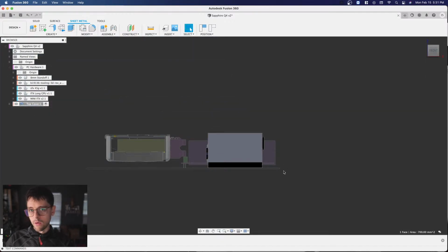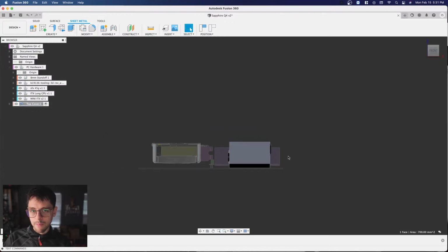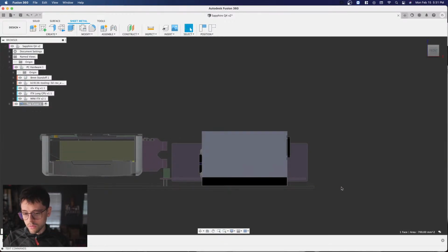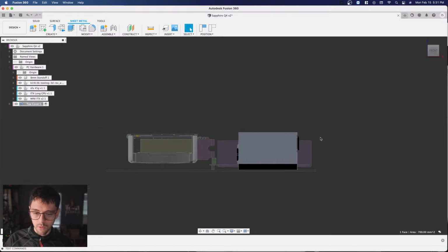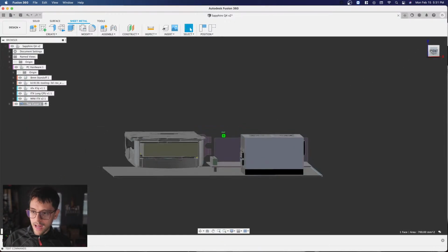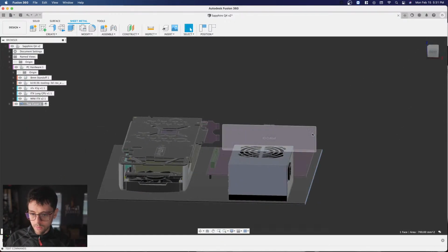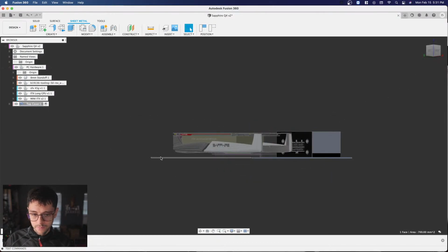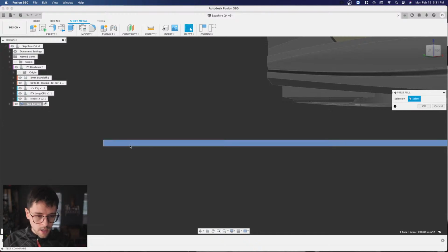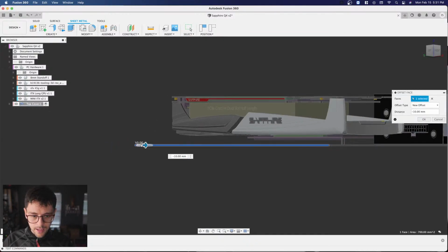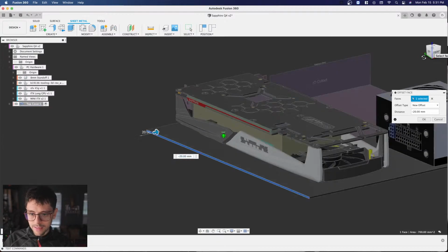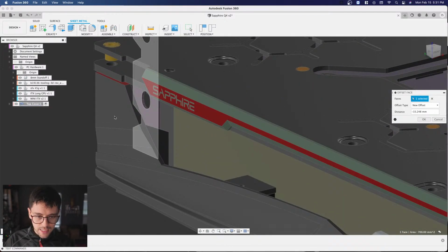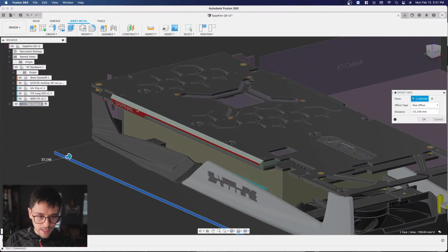So I'm good there. I know that's how I want it. I'm going to make the other flanges 10 millimeters when they're going over. That's cool with me. 10 millimeters, in my opinion, would be the minimum that you could easily assemble this computer case for. Anything lower than that, it's going to be quite difficult getting it around this motherboard. And it's also going to cause tear outs when you go to bend without, again, special tooling. Let's do the other side. Same kind of thing. Drag it just a little bit, and then I can snap it to whatever face I want, and then we're going to use this edge of the graphics card.